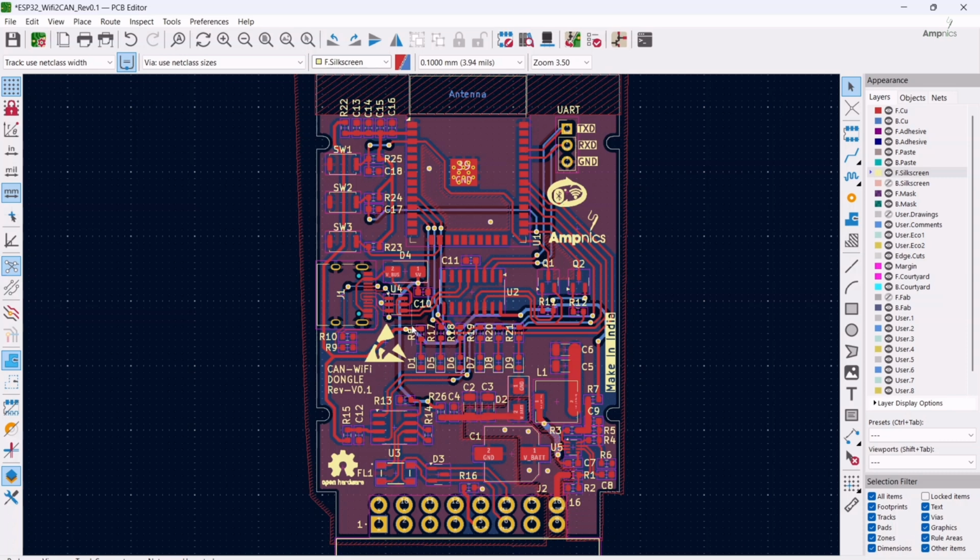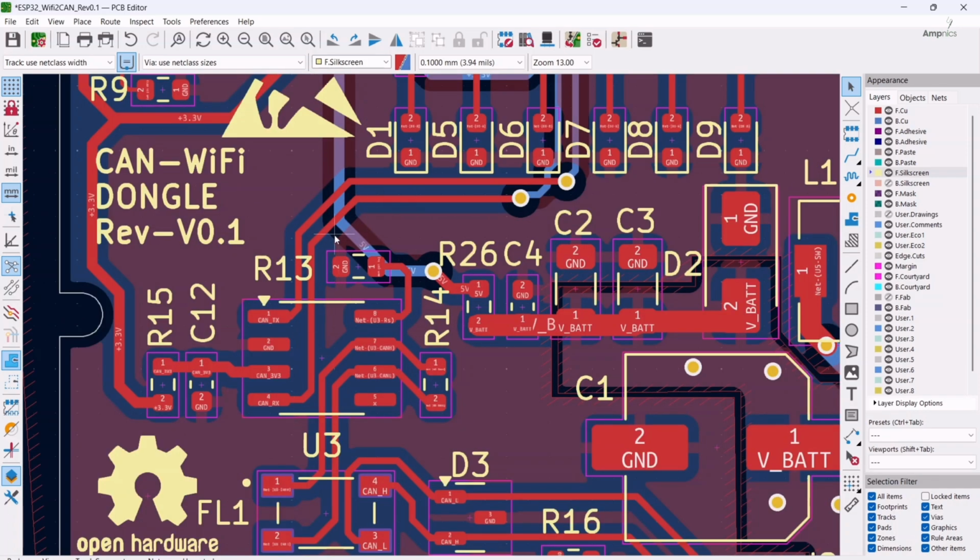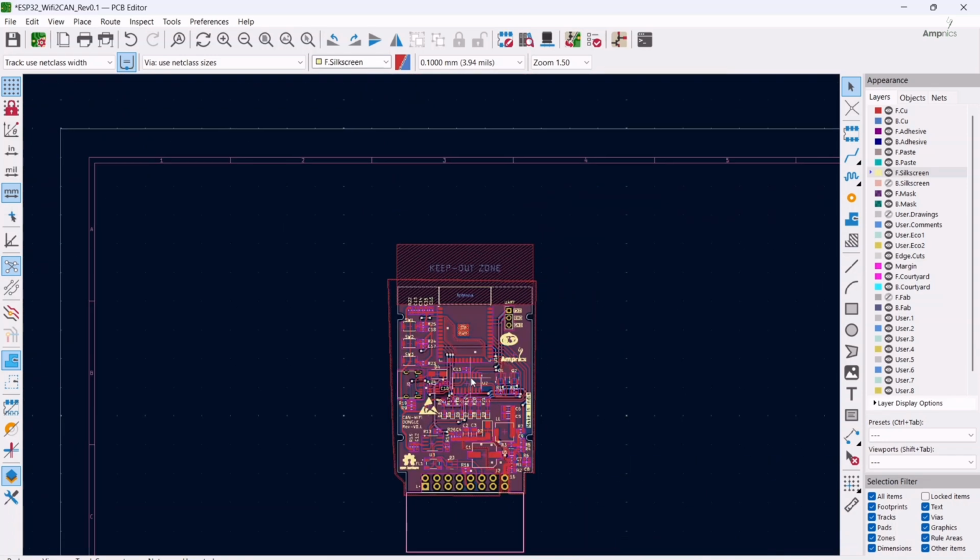So as you can see, there's only one thing to notice: in each and every track there's no 90-degree curve. Okay, there's no 90-degree tracks. Each and every track is only about 45-degree, because this is the best approach to make the tracks. So you always have to keep in your mind, if you make it more circular, that will be better, but it is always to go with bare minimum, that is 45-degree. So always you have to make the tracks like this only. You have to avoid direct 90-degree connection. This is one of the best approaches to make the tracks.